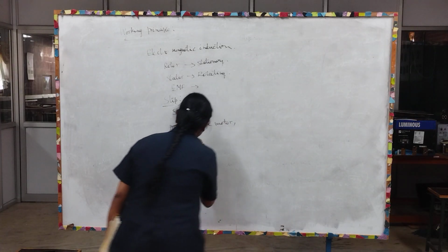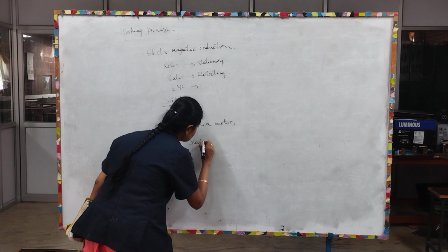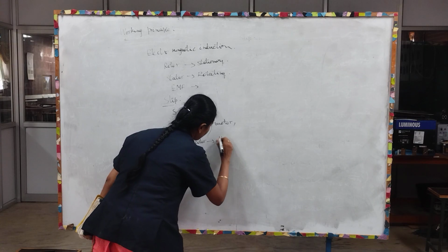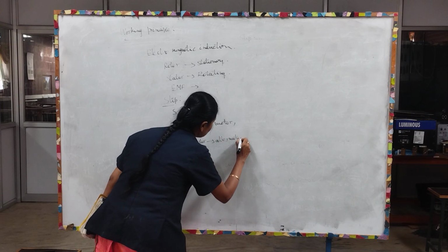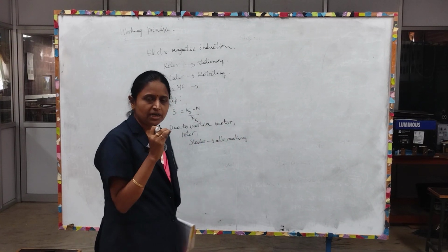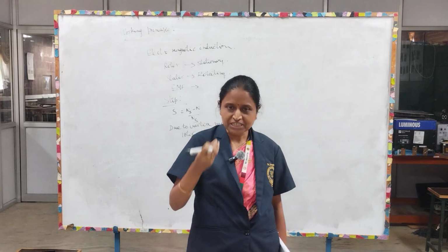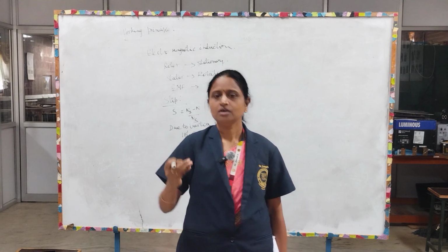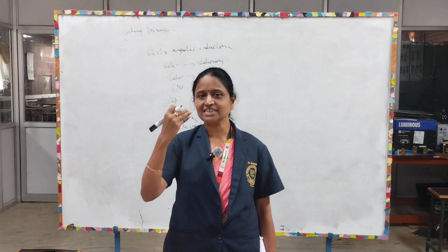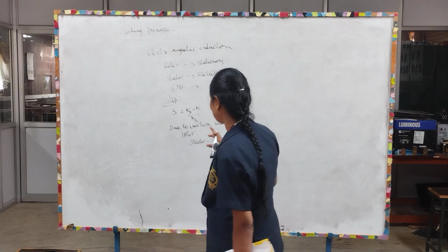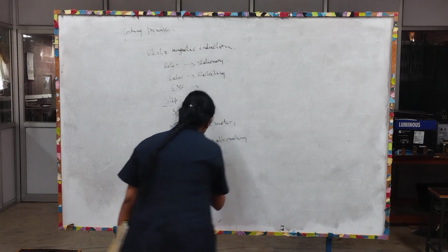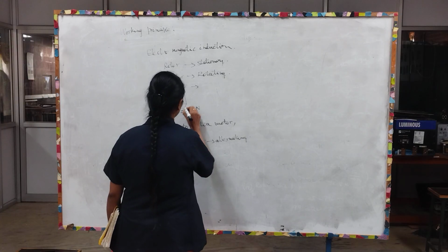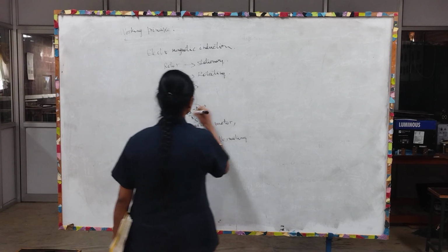The stator has a rotating flux, but the rotor won't catch up with the speed initially. It will take some time to overcome its inertia, so the rotor speed won't be the same as the synchronous speed of the stator. That's why we have a difference in speed.